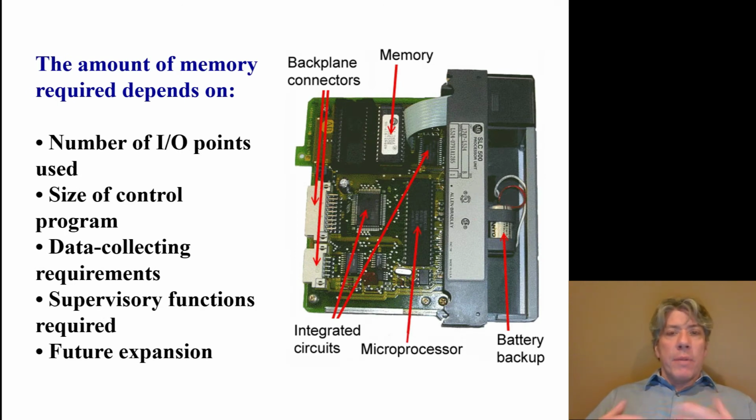Now, the amount of memory you really need depends on how big of a program you plan to write, and how many I/O points you have, because the more I/O points, the more memory you need. It also depends on how much data you want to store in the PLC. Maybe you need to collect data. Maybe you're running a machine where you're making widgets and every widget needs to be measured. If you make 1,000,000 widgets in a day, you're going to need enough memory to store those 1,000,000 points of data, or you're going to have to go in between and download it or something.